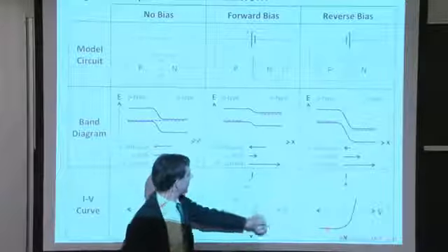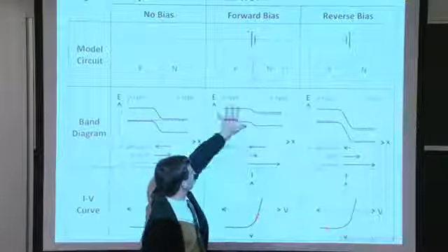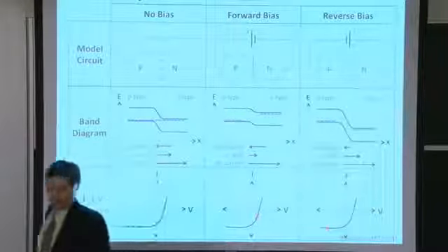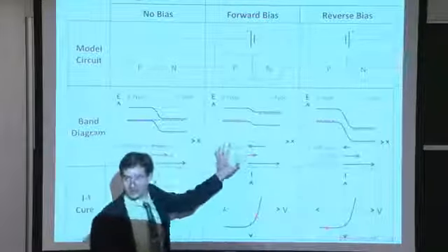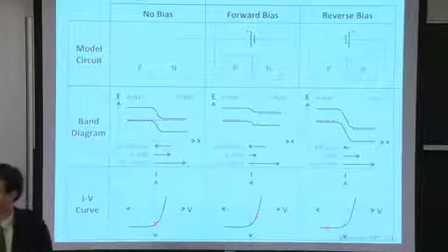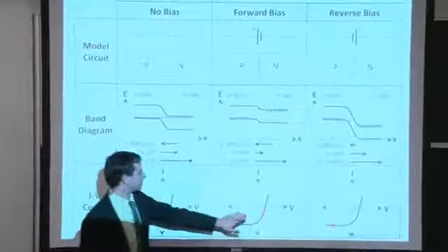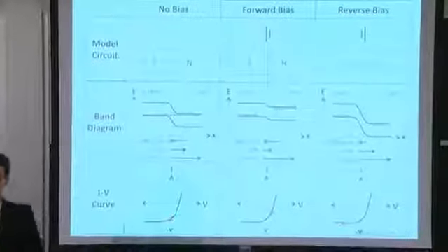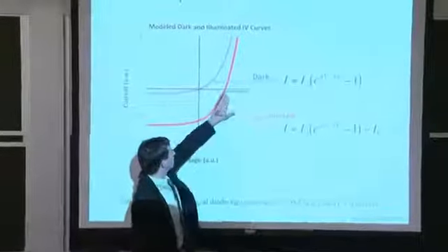Right? So the voltage is favorable, and the current is also favorable, because now we have light coming in, and this generation current is creating carriers here in the P-type that can then be driven toward the N-type because of the built-in field. So the conditions are just right under illuminated forward bias conditions to drive power through our external load. Under all other conditions of operation of the solar cell, we're putting power into the device, not getting power out of it. This fourth quadrant over here, this forward bias illuminated case, is the only case in which usable power is coming out of our solar cell. So that's why we focus on this fourth quadrant right here.